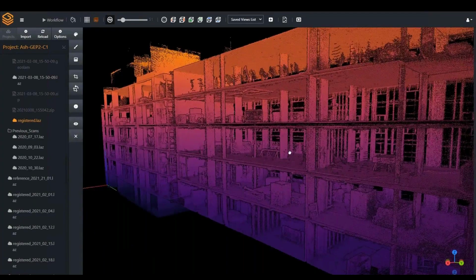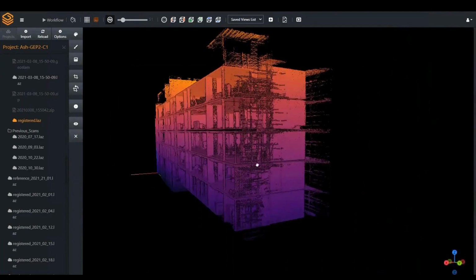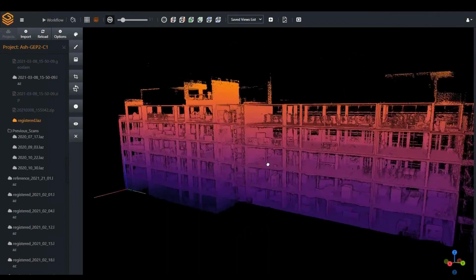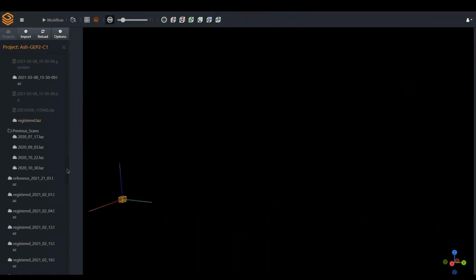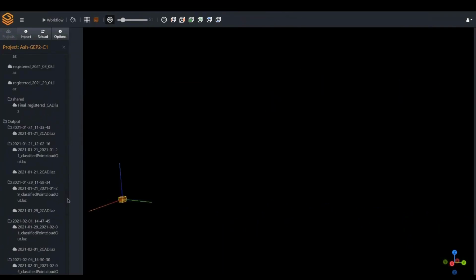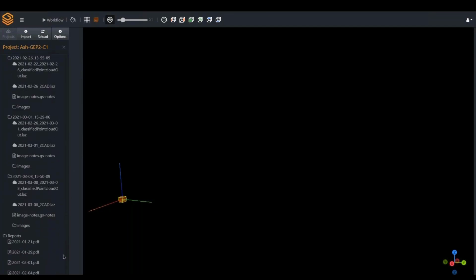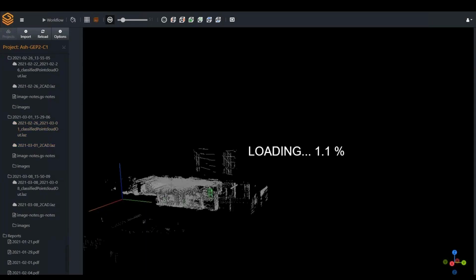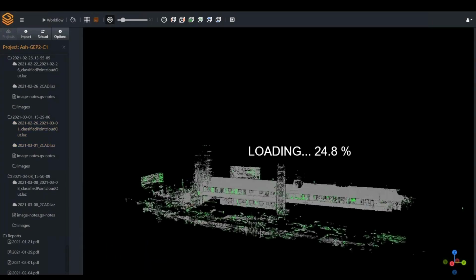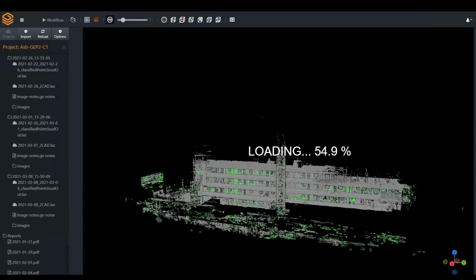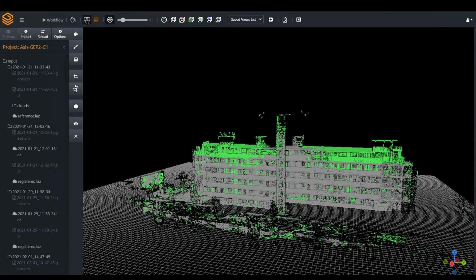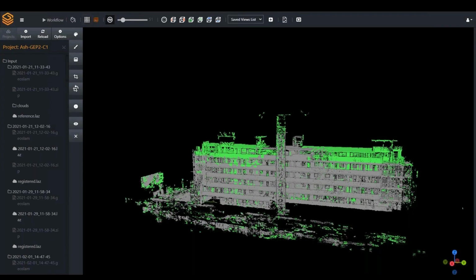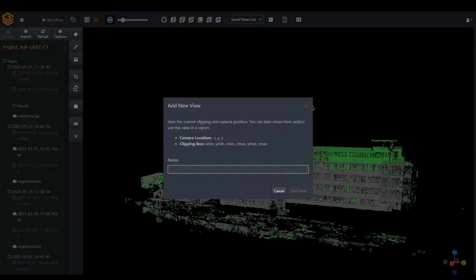And this is something that Connect produces automatically, but we also went a step further and produced automated analysis of the data. So once this point cloud is processed, we automatically compare it to a previous point cloud of the same building, of the same site, and we are able to generate a so-called scan-to-scan comparison, where anything that's new, any progress, is automatically highlighted in green color. So here we are looking at the scan in early March compared to the last scan in February.